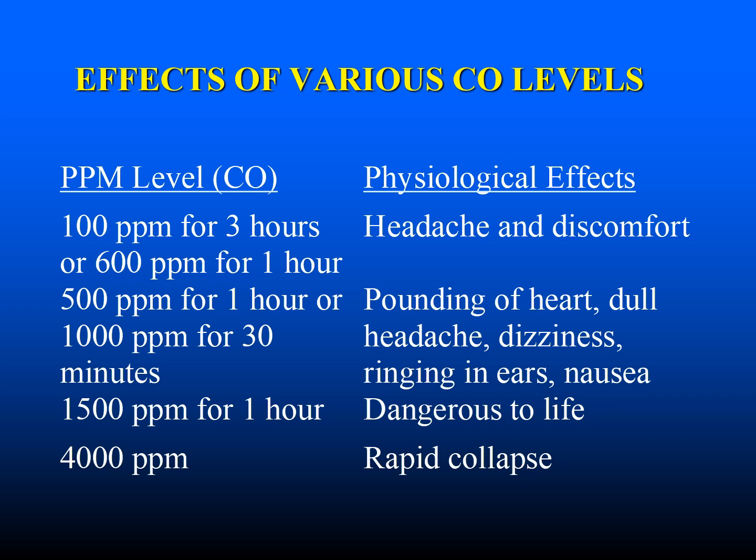At 500 parts per million for 1 hour or 1,000 parts per million for 30 minutes, they will experience a pounding of the heart, dull headache, dizziness, ringing in the ears, and nausea. Exposure up to 1,500 parts per million for 1 hour becomes dangerous to life, and at 4,000 parts per million, it would cause a human being to collapse.